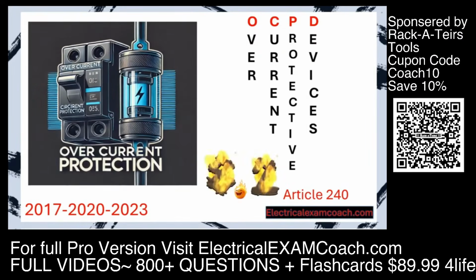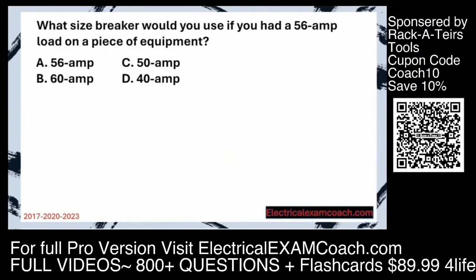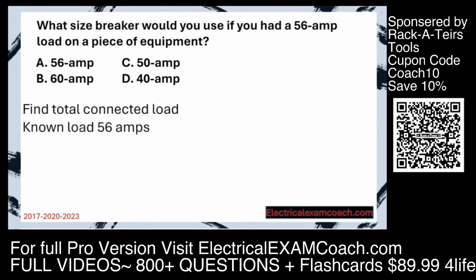And in this lesson, we're going to learn how to size overcurrent protective devices for non-continuous and continuous loads. Let's get to it. What size breaker would you use if you had a 56 amp load on a piece of equipment? Step 1, find the total connected load. The known load as of right now is 56 amps. Now we check for demand factors.